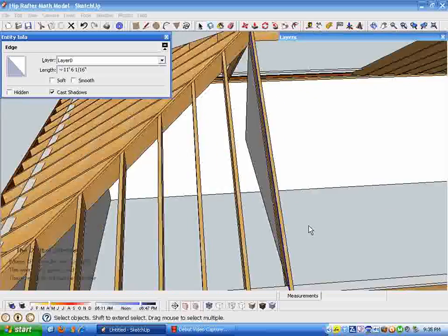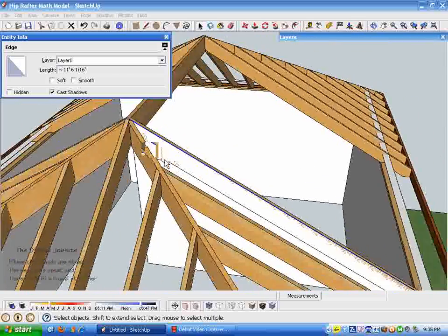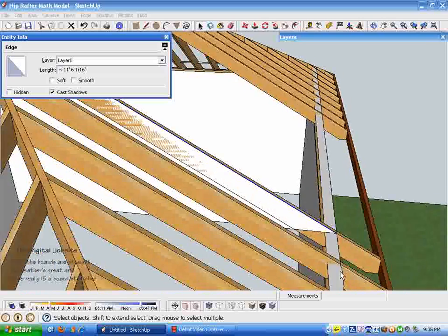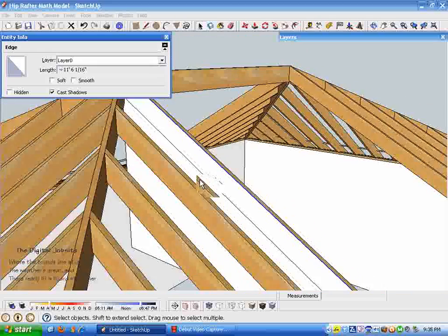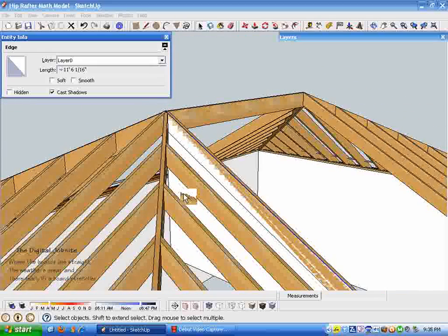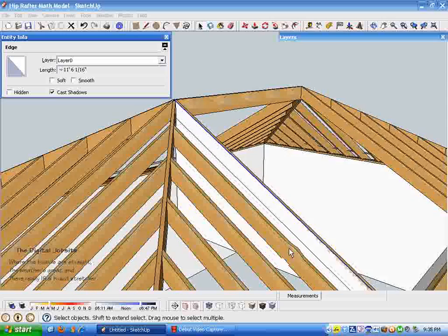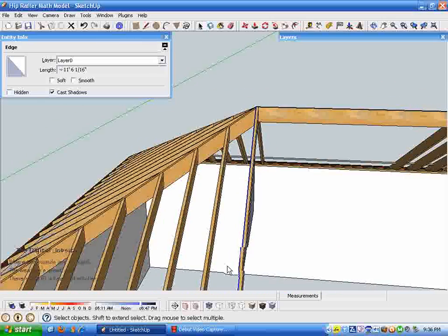And that is the length of the rafter on a diagonal to get from the face of the ridge to the outside of the wall sheeting, in this case the dimension that I used for the run of the rafter. So that's all pretty simple to go. It's obviously faster to click a few keys on a calculator to come up with that specific line for a common rafter.